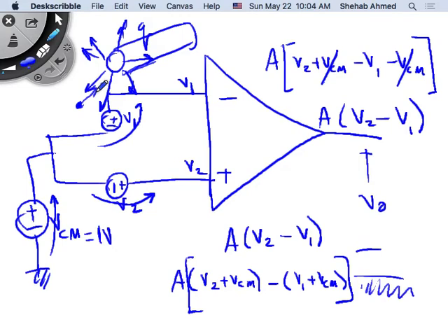But what I'm trying to say is that anytime you have current flowing in a conductor, meaning charge deposited on the surface of a conductor, it will cause a voltage difference between any two points in space around it. Now let's say you put another conductor at that point in space. That conductor is within that electric field. It will have a voltage difference between it and the other conductor because of the electric field you've placed it in.